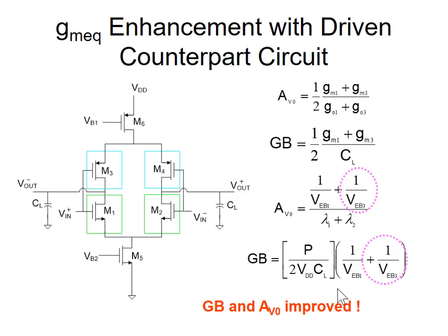Cut your power dissipation by a factor of 2. If you look at a lot of data converters that have op amps in them, a major portion of the power dissipation is in the first stage op amp in those structures. If you can reduce that power by a factor of 2, you will come close to a factor of 2 reduction in the power required for your data converter. So it's non-trivial.